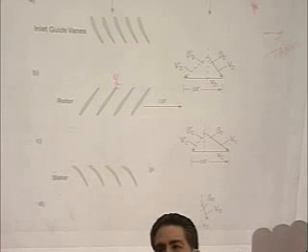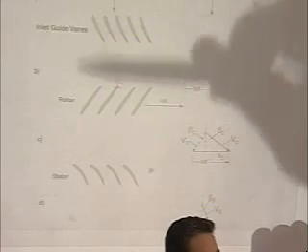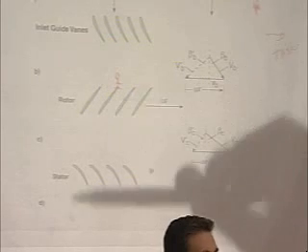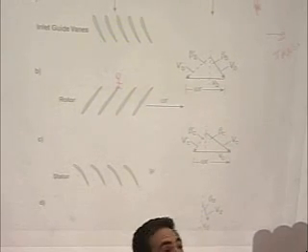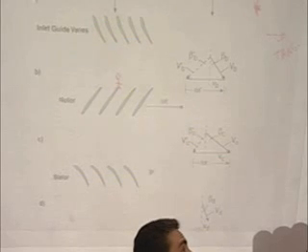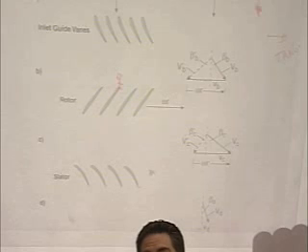And I warned you about this. The way you have to solve these problems is you go from stationary to rotating frame to stationary frame to rotating frame to stationary frame to rotating frame. So you have to do a transformation between those frames, between each and every blade row.